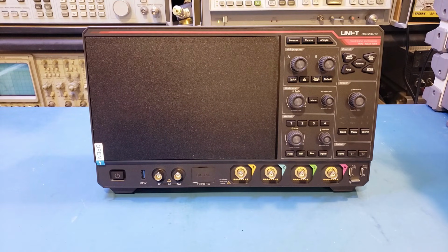In some areas, the Rigol has an edge. For instance, the maximum frames of waveform recording is 500,000 frames on the Rigol versus 400,000 frames on the UNI-T. And by the way, that is for the segmented memory feature. And the vertical sensitivity is 100 microvolts per division on the Rigol versus 500 microvolts per division on the UNI-T. Of course, I don't have a Rigol DHO 5104 here in the lab, so the comparison I mentioned here was strictly from the official specifications. Nevertheless, this should give you an idea of how similar scopes on the market today compare with the UNI-T MSO5000HD series.